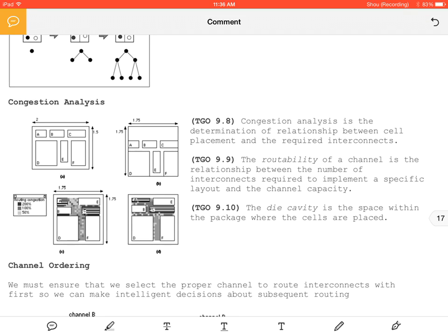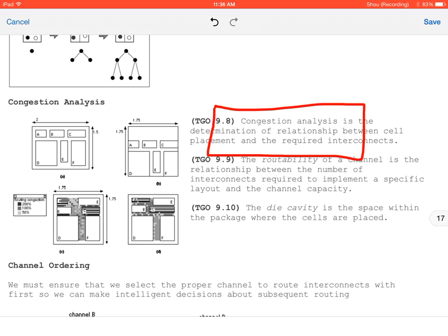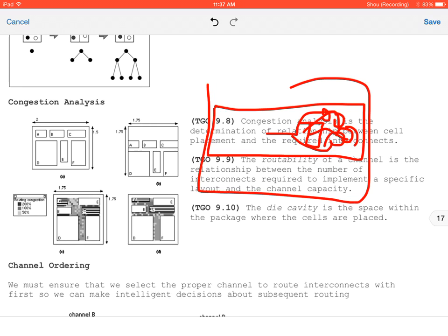It's easier to route the wires. Yes, easier to route the wires. The reason why is if we did this as a rectangle, and we put one thing here, it's very possible that your floor plan will have a lot more cells that need to be accessed. Whereas if you make it a square, or even a smaller square like this, your general floor plan is going to move it over here naturally. So the square is the best shape in terms of floor planning algorithms.